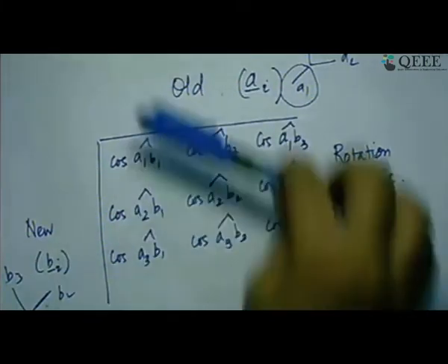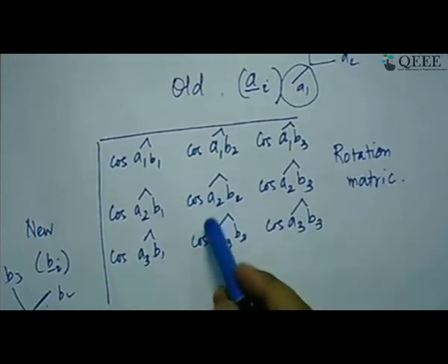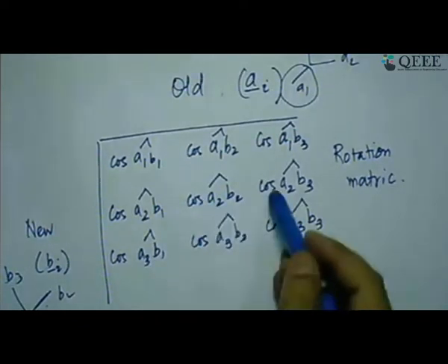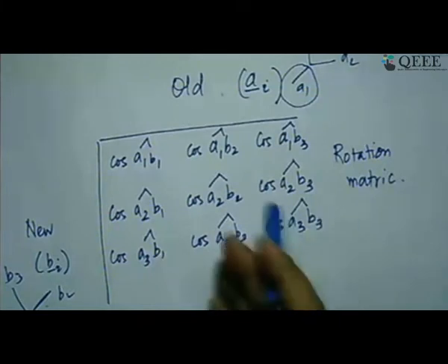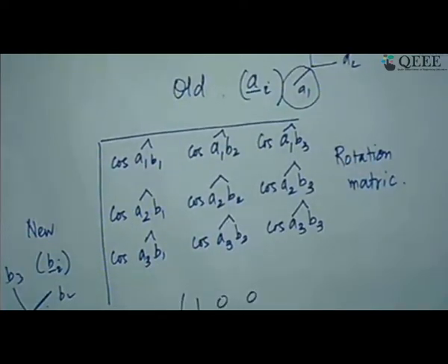And if you have the rotation matrix, as you can see, the rotation matrix consists of only direction cosines, and then we use the property from trigonometry that cos 90 plus theta or cos 90 minus theta has some relationship to sin theta. That is how the rotation matrices are typically written, right? Rotation matrix is 1 0 0, 0 cos theta sin theta, 0 minus sin theta cos theta. Okay. There is sometimes confusion whether the minus sign is here or here.